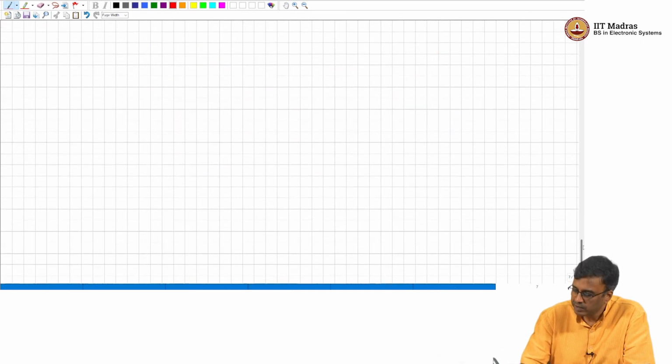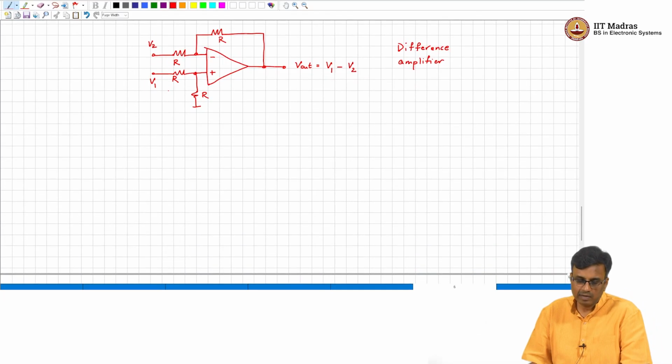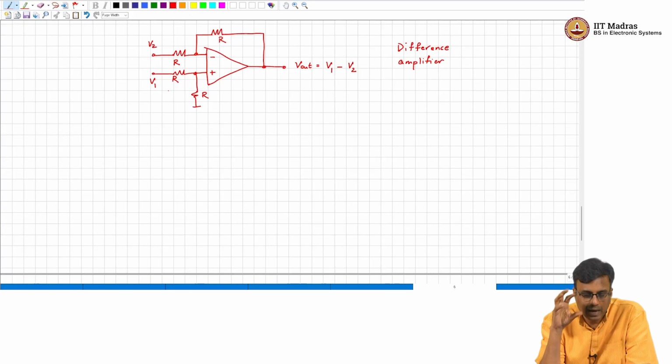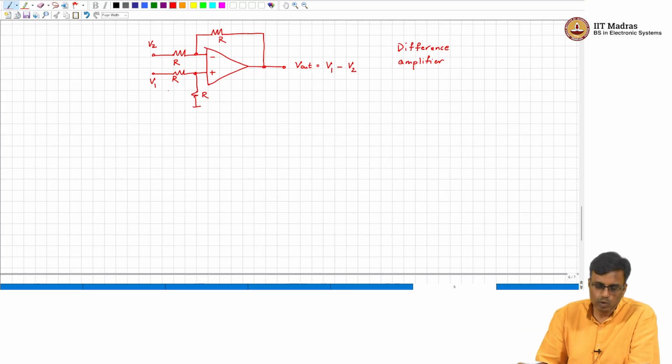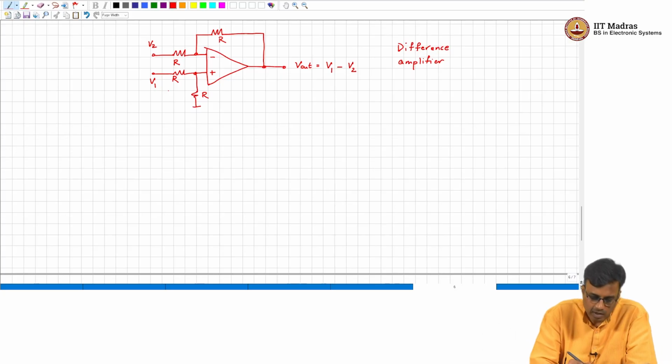So, now with resistive circuits, if you want the op amp to behave with the difference between the 2 terminals being 0, you must make sure that there is negative feedback around the op amp. Okay. So, now let us do an example where we do not know the sign. I will give you a circuit, we do not know the signs of the op amp. Let us try and figure out what the signs must be, so that there is negative feedback. So, here is an example.